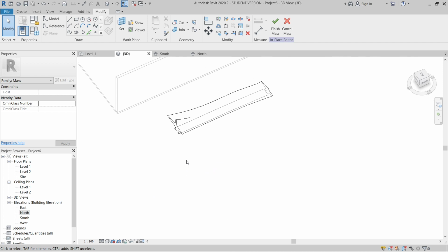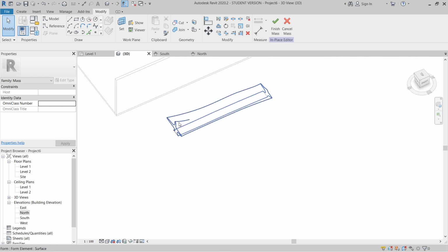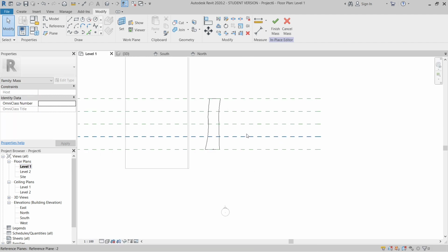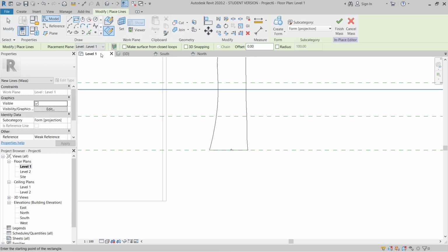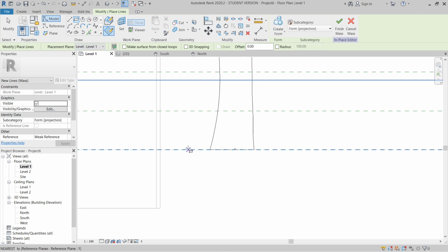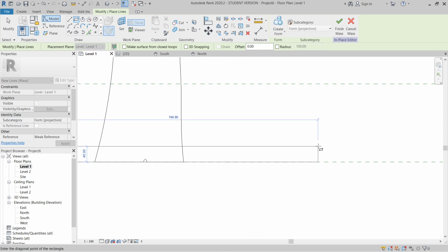And now what is left is to create that ribbed geometry. So how do we do that? Essentially we'll create these void forms and then create multiple copies of it, so it looks like it's ribbed throughout the geometry. So to do that, you go to floor plan again and now create a rectangle. Make sure it's at level 1, that's fine, and create a tiny rectangle.